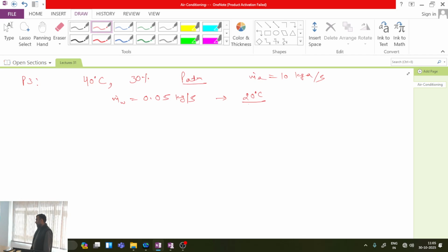So all the water is evaporating, and in the vapor state it is mixing with the air. Is this point clear? So ultimately the heat from the air is utilized to evaporate the water. Because the duct is insulated, there is no external heat coming, so heat from the air is only required to evaporate the water. Then we have to find the outlet state. Okay, how to start the problem? Now you should tell me the steps.